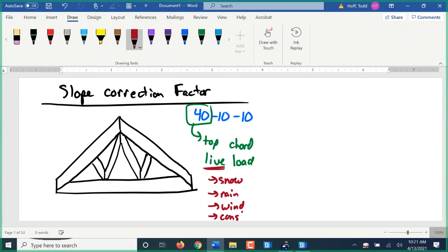Construction load. While you're building these houses, or when you have to repair or redo the roof, you're going to be on that roof. You're going to have equipment up there, materials. That's construction load. You don't want more than 40 pounds per square foot on that roof for that construction load, or it's over its design limits. I know a lot of people that have their shingles delivered, and they stack them all along the peak of the roof. That's not good.